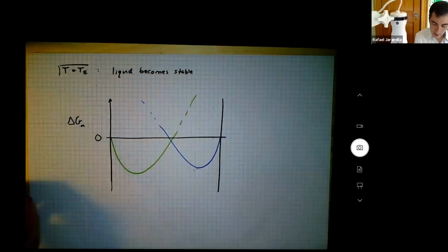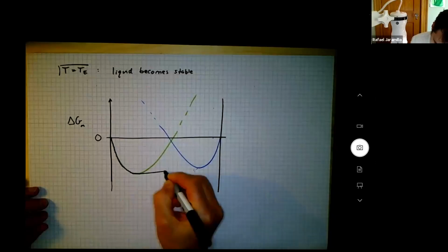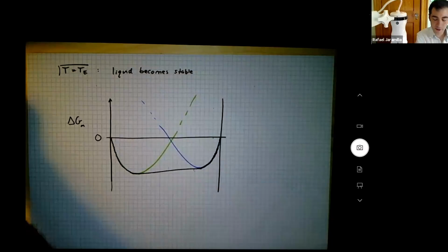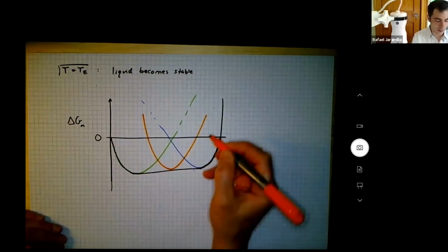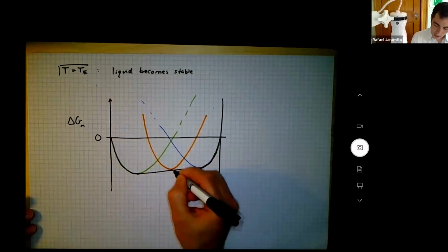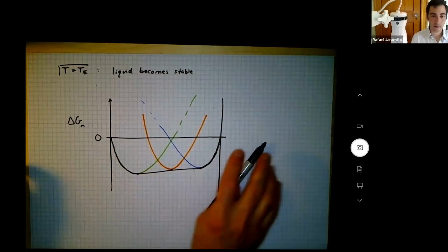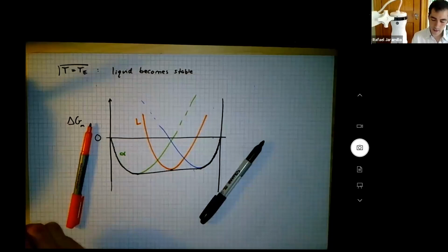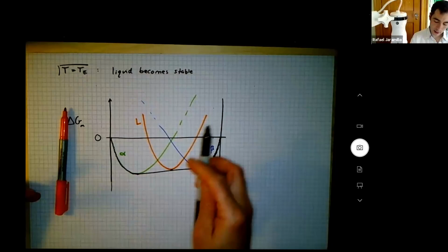Now cheat a little bit here. Here's my taut rope in this case. But now the liquid phase is just barely stable. So now I have a unique point of a common tangent that's common to 3 phases, right at that eutectic point. Here's liquid, alpha, beta. Here are my points of common tangency.